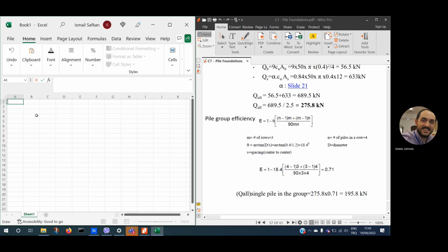The benefit of stone columns compared with piles is that when you do the compaction of the stones inside the soil, you don't have a reduction in the group efficiency, because you basically apply compaction sideways and you don't have reduction because of the distortion of the soil. That's a good benefit that we can utilize.